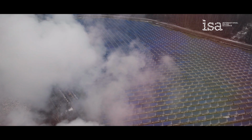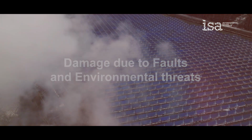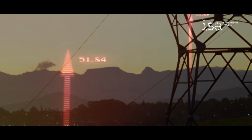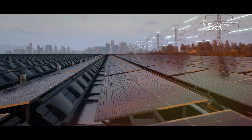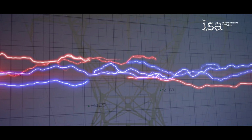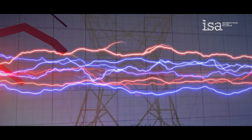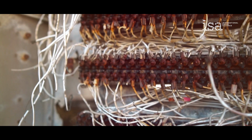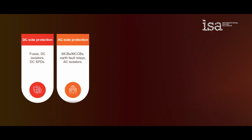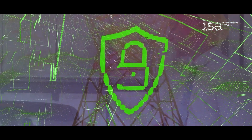PV plants require electrical protection to prevent damage due to faults and environmental threats. The main protection categories are overcurrent, overvoltage, surge, earthing/fault protection, lightning protection system, LPS, and anti-islanding. DC side protection: fuses, DC isolators, DC SPDs. AC side protection: MCBs, MCCBs, earth fault relays, AC isolators.